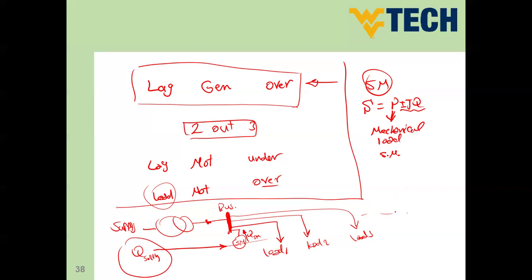Is it going to absorb active power from the grid? It's going to absorb just the amount of active power that will be consumed in the motor losses. You remember that if the motor is working at no load, we still have some core and copper losses. So we have P core and P copper in the synchronous motor. But this is going to be a small value.